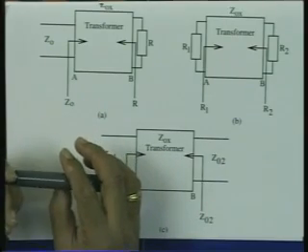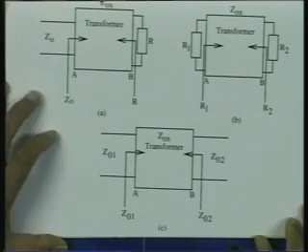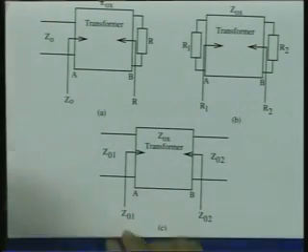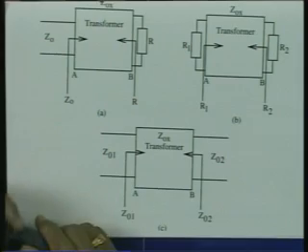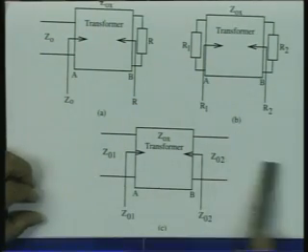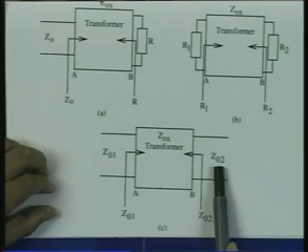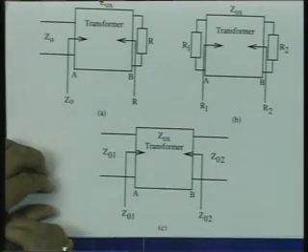And there is a maximum power transfer. The third and important case would be, suppose I have two long transmission lines which are to be connected. A joint has to be formed between these transmission lines. If the length of the transmission line is very large, then the input impedance of this will appear almost the characteristic impedance of the transmission line.